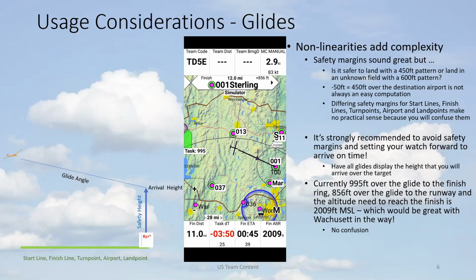So I landed in a field by the fact that at the end of the day, when I was really tired, having had a harrowing last hour, all below 1,500 feet, I didn't have the emotional energy left to do all those calculations on what the margins were. So ever since then, I've been particularly fastidious about removing margins, and in that glide situation, the number I see on the screen is the number I'm going to deal with.